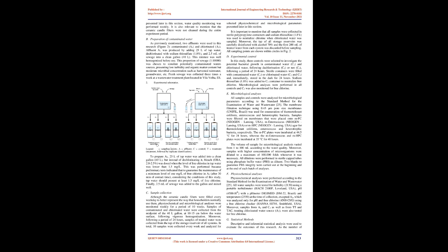Moreover, following a period of 24 hours, samples of treated water were collected from the tap of the storage reservoir of all systems. In total, 10 samples were collected every week and analyzed for selected physicochemical and microbiological parameters presented later in this section. It is important to mention that all samples were collected in sterile polypropylene containers and sodium thiosulfate, 1.8%, was used to neutralize chlorine when chlorinated water was sampled.